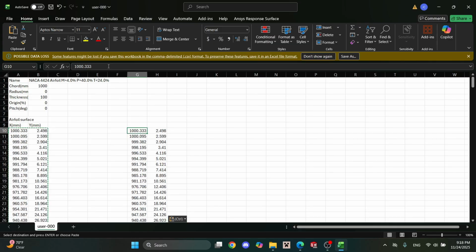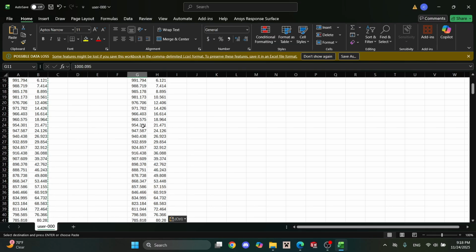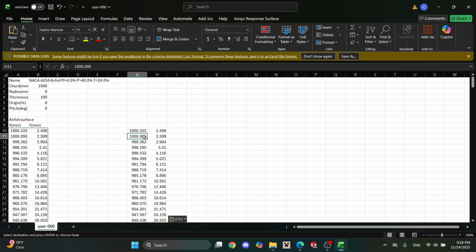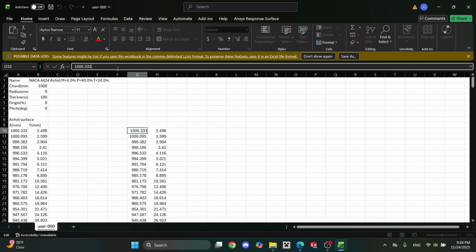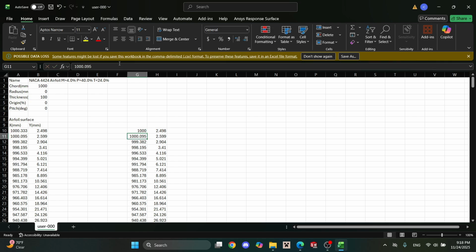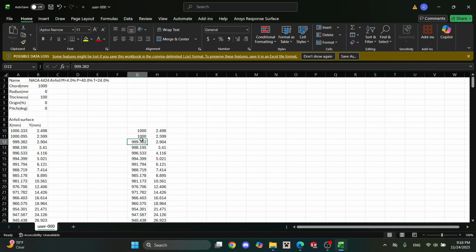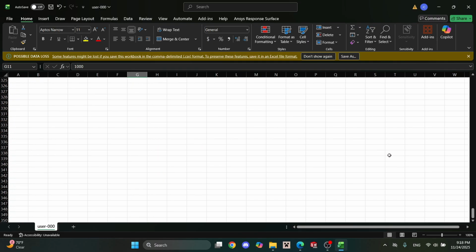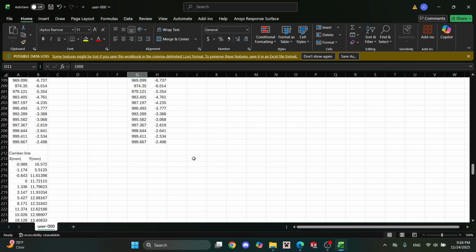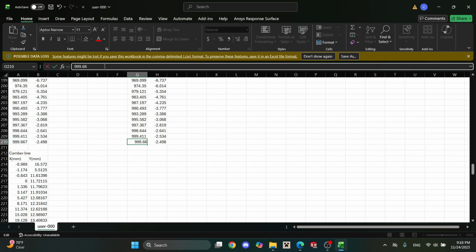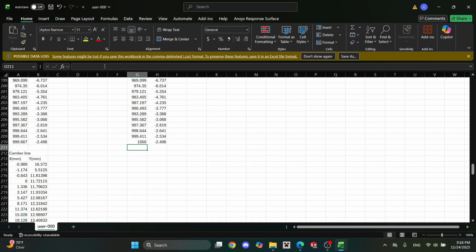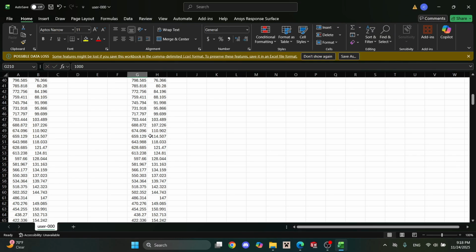From trial and error, I found that for the points that have an X value greater than 1,000, you need to lower them down to 1,000, so that it won't cause any issues. I don't know why, but even though my chord length is 1,000 in Airfoil Tools, it'll create an airfoil that is more than 1,000 chord length by a very slight amount. This I'll also fix to be 1,000.